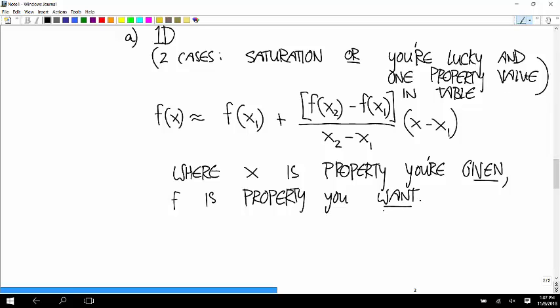And sometimes you have to do this. Usually your x value, the one that you're given, is temperature or pressure. But that doesn't have to be the case. There have been a couple of problems where you're given, say, the specific internal energy. Then that specific internal energy that's out here in the table somewhere is what you use as your x value, and you do it sort of like a reverse lookup, and your f is the temperature or the pressure. So it doesn't have to be that your f is what the table is indexed by, although that's more common.